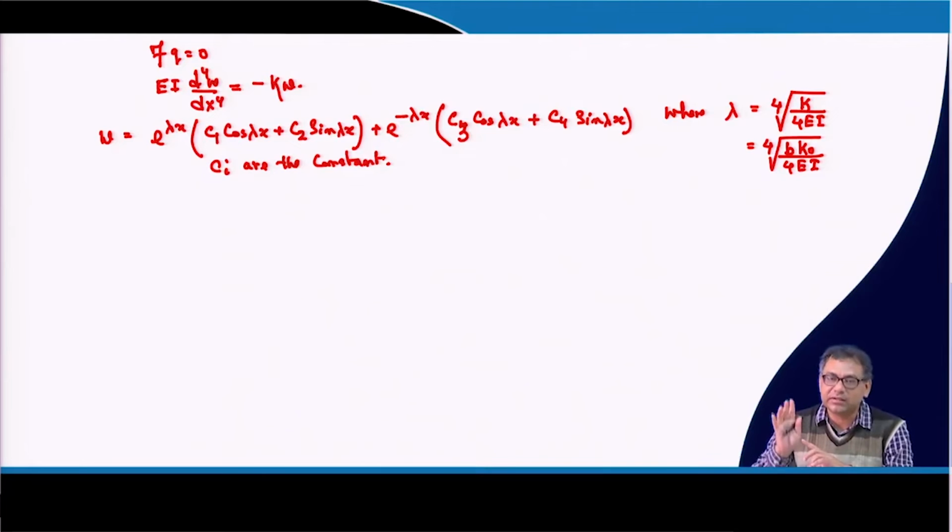In such conditions, piles will be idealized by semi-infinite or finite length beams, and then we will determine the settlement of the pile due to the lateral load. So, that concept is very important, so that later on you can use it to determine the settlement of the laterally loaded pile.